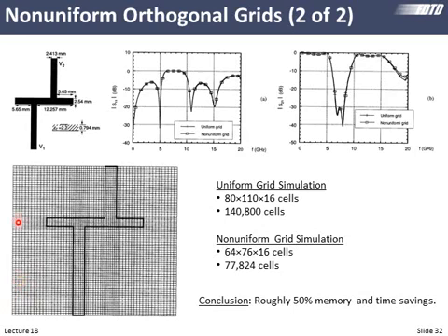We're making the spacing very tight all the way across. We're also making the spacing very tight here all the way down, and the spacing a little bit tighter here all the way down. So we have a very coarse grid in the corners and a little bit in these middle regions. So we get away with fewer points, but we're still resolving the field where we need to. So in this particular case, it's about 50% more efficient. That's pretty big for the little impact it would have on your formulation and implementation.